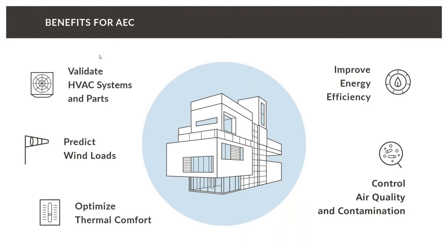For small buildings, you can use some tables, but for larger ones, you need to provide real test results. Usually what people do is run wind tunnel tests with small scale models, which is super expensive. Using CFD, you can make a simulation of the full scale model, including the surroundings, and it's much faster and much cheaper.